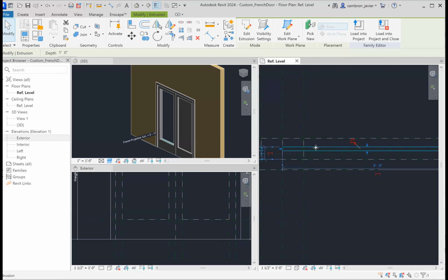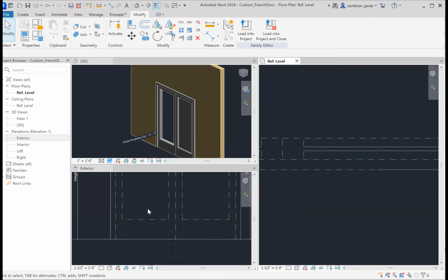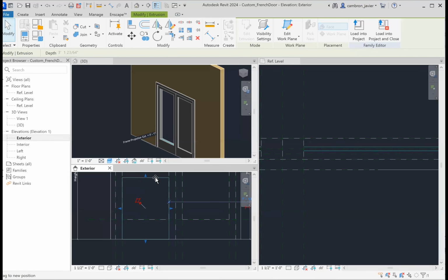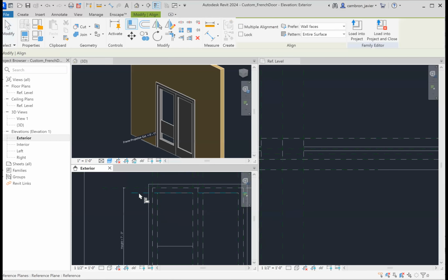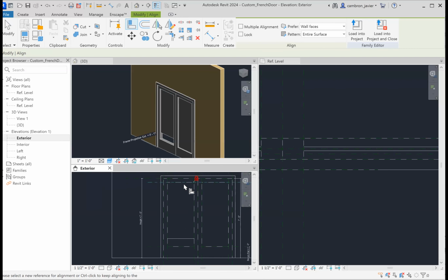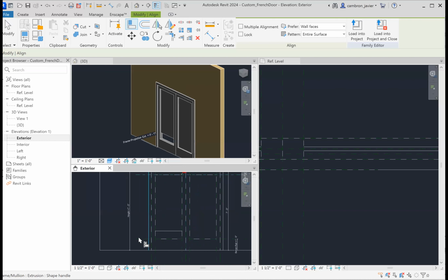Okay. So let's go ahead and click on it, and let's move it from over here to this side. And now we could lock it. Okay. Now let's come back again over here, hit the tab key. There we go. I'm going to go ahead and bring that up. And while I'm at it, so that I don't hassle with it later on, let's bring the bottom up as well. So now I'll use the align tool, up top, right there, and hit the check mark. We're going to do the same thing over here, align to the bottom rail, align right there, and hit the lock pad.